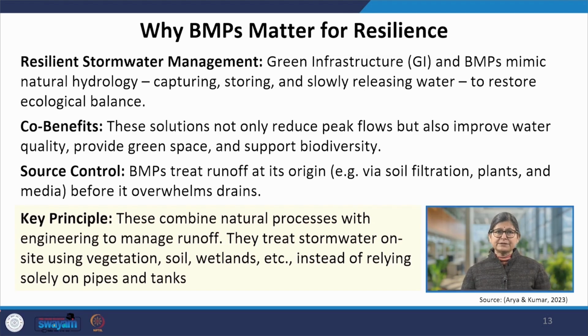The source control, BMPs treat runoff at its origin via soil filtration, plants, and media before it overwhelms the drains. So, the key principle for the BMPs is that they combine natural processes with engineering to manage the runoff. They treat stormwater on site using vegetation, soil, wetlands, etc. These are the strategies instead of relying solely on pipes and tanks.